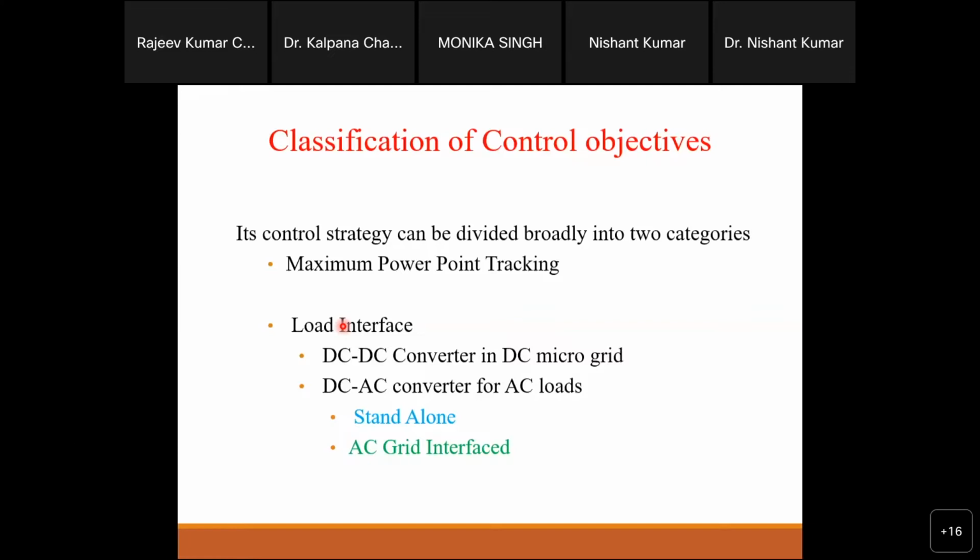First of all, the first grid norm is that the frequency should be according to the grid frequency, so that our system will synchronize accordingly. The voltage should also be according to the grid code or grid norms, or in the worst condition, within the limit of that. If we are thinking of three phase, then definitely phase matching is another grid code. So these are the key parts of integration according to the grid code on the connection side.